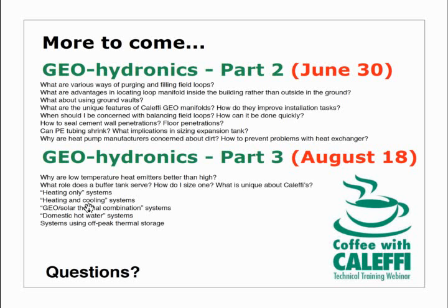Yeah, radiant cooling is, again, a sector of the market that is growing. Initially in the larger building sector, but there's a lot of interest in radiant cooling now in residential. It certainly is a good tie-in with a water-to-water heat pump as the source of the chilled water, but as Bob points out, it's critically important that you avoid the dew point temperature on any radiant surface.